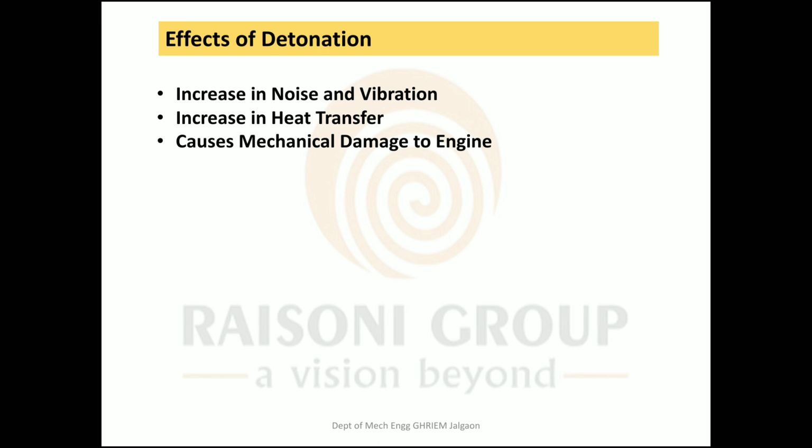In severe cases of detonation, increased cylinder and piston temperature cause collapsing of the piston crowns and sometimes burning of the cylinder head. Prolonged running of the engine under detonating conditions causes loosening of the valve insert rings in the cylinder head, burning of the sides of the piston due to blow-by of very hot gases, and gumming of the piston rings in their grooves.